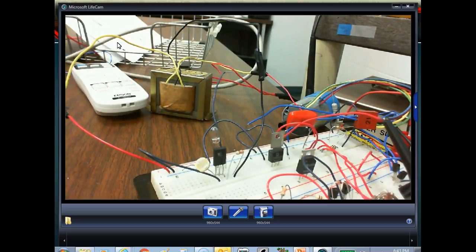You understand? So transistors work great if we operate them as a switch, we don't have to heat sink them as much, because they're either what? They're either on or off. It's when we get those transistors in that active region that starts giving us problems.